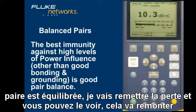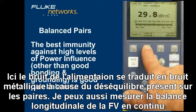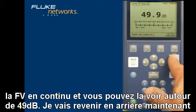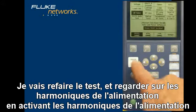Okay, I'm going to put the fault back on the tip side again, and you can see our noise goes back up. What is happening is that high power influence noise is actually translating into metallic noise due to the unbalance that was on the pair. I can also measure the continuous longitudinal balance, and you can see it's around 49.9. Okay, I'm going to back out now. I'm going to rerun the test.